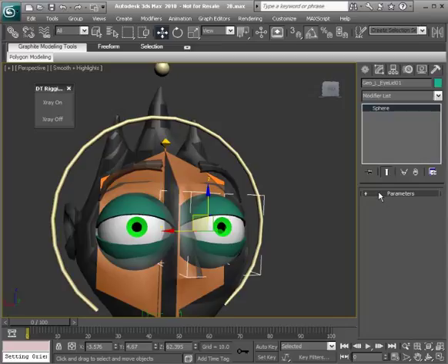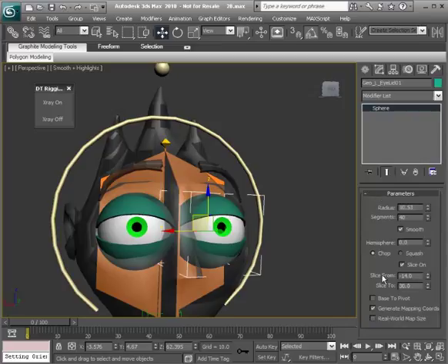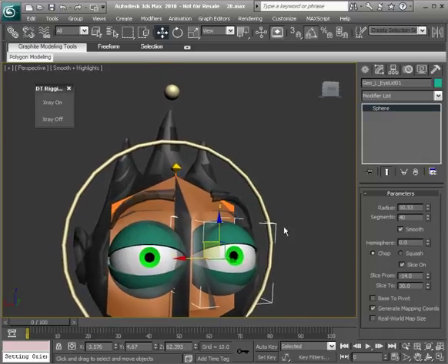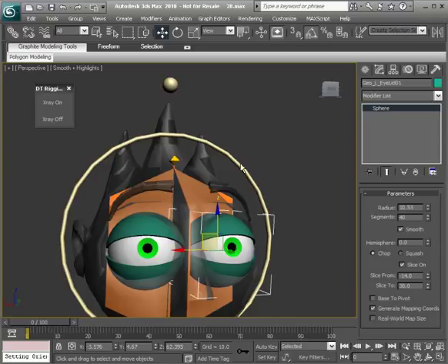So how are we going to do this? Well, we need to use simple math here. We need to, again, remember that we want to keep this at -14, but at the same time we're plugging this into a control with a value of 0. So to keep this at -14, we simply need to wire this into this control and add a -14 to our expression. So it's simple. It's as simple as saying -14 plus 0, which gives us that same value. So we'll do the same thing with the slice 2. That's simply going to be +30. So let's go ahead and plug all of this in so you can understand clearly what I'm talking about.